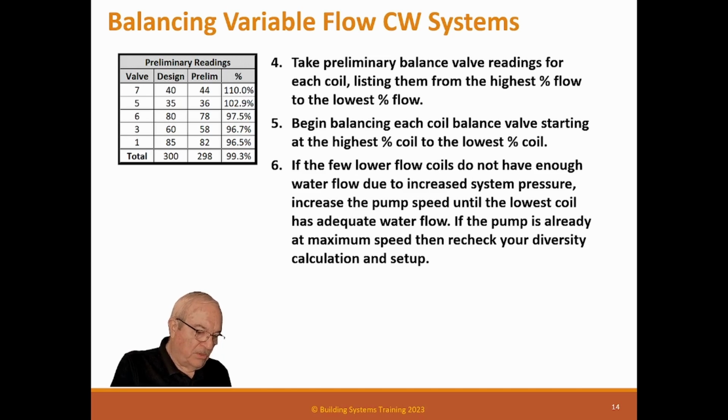Now, normally VFD pumps are run to 60 hertz to full speed. Hopefully the pump's not a 3,600 RPM speed pump. But if the pump's a normal 1,800 or 1,750 RPM pump, you can actually speed it up beyond 60 hertz. If you need just a few more GPM, you can run it at, instead of 60, 65 hertz without a problem. Pumps will do that, and the VFD will do that without a problem. Now, you may have to have someone help you do that. You may have to go into the software setup to allow it to go beyond 60 hertz. But you can do that if you have to.